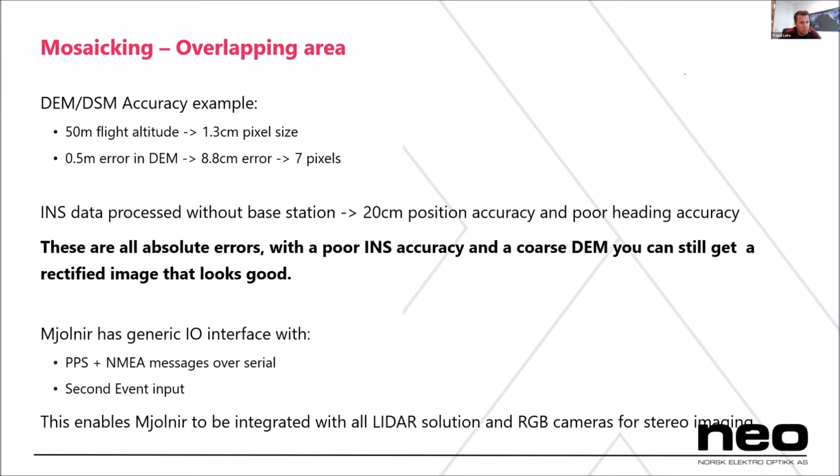That's why we are supplying LiDAR systems and photogrammetric systems that are mounted on the UAV systems, because typically we had customers, right, that have a huge demand for accuracy, and then they come with a 30-meter resolution elevation model, and yeah, then that will not work, right? The image will look good, the rectified image will look good, but co-registration between flight lines will never work with such a coarse step.